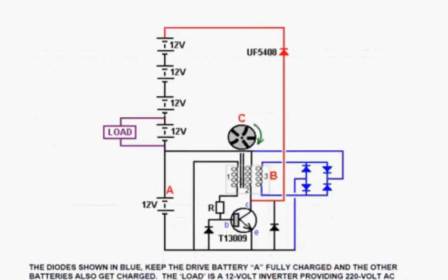Now, he started off with this circuit. He built a rotor, and in the rotor he put magnets, and the magnets spin round past a coil which has got a metal core. As it goes past, it powers the coils. It feeds, like the Joule thief, the current to the base of the transistor, which drops the resistance between the collector and emitter to 0, which drives a strong current through coil number 2, and powers up coil number 3 as well.